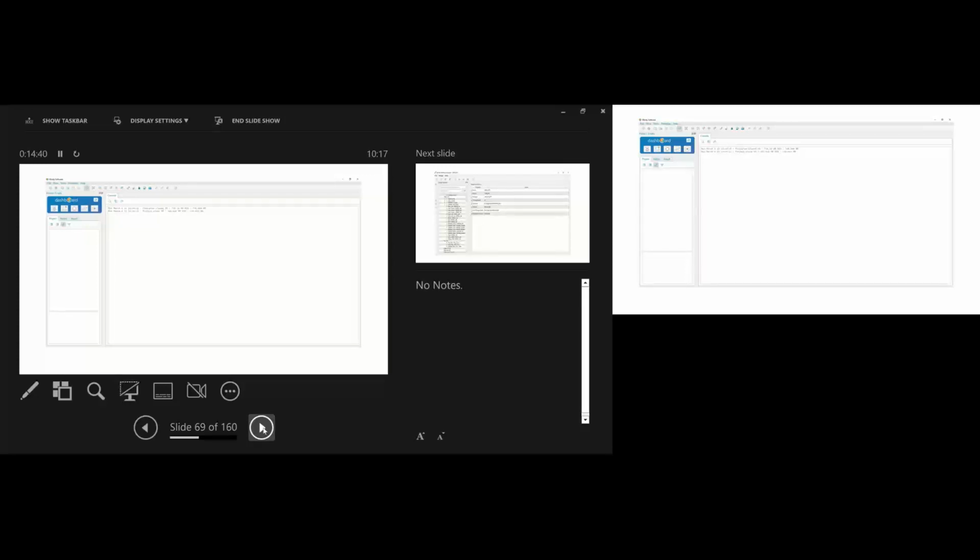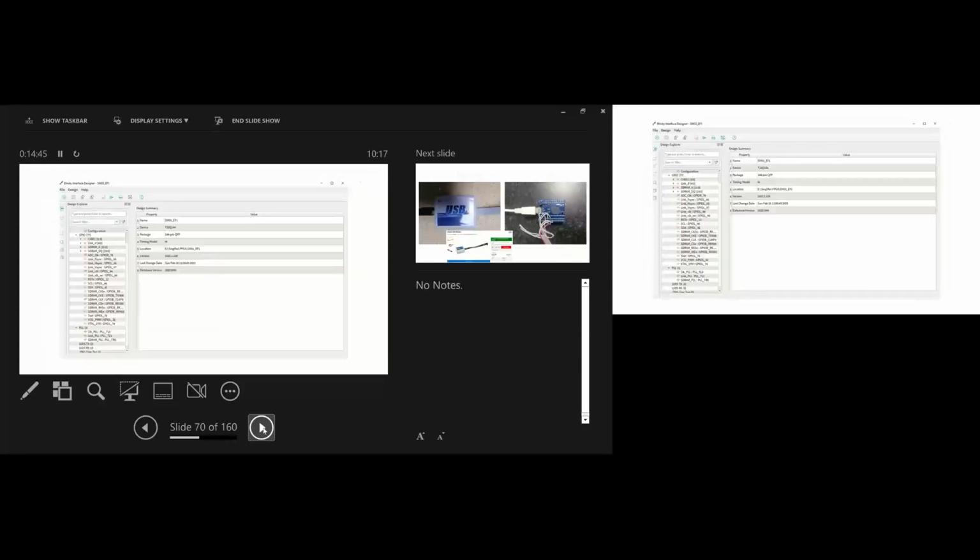The only thing was, how do I assign the pins? There was no little graphical thing that Quartus has where you just put the pins across onto a package diagram. FPGAs have decided PLLs, tri-states, I/O assignments are not part of your Verilog code. A sort of wrapper thing that you've got to go and find, and you define it separately. Well, they were originally designing FPGAs for inclusion in larger SoCs. Right. So that's why it's separated out.